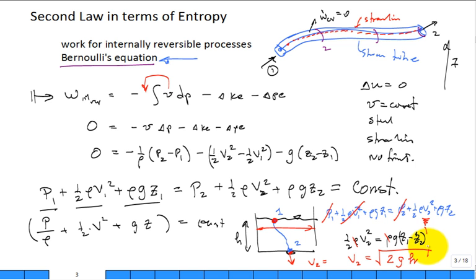You do the same thing now in fluid mechanics. Well, you'll do this a lot more than that in fluid mechanics, but at least that's the same thing in thermo. So there you go, Bernoulli's equation linked into our energy equation. For an internally reversible process, with a number of assumptions, steady state, and there's no work. So that work term goes away.